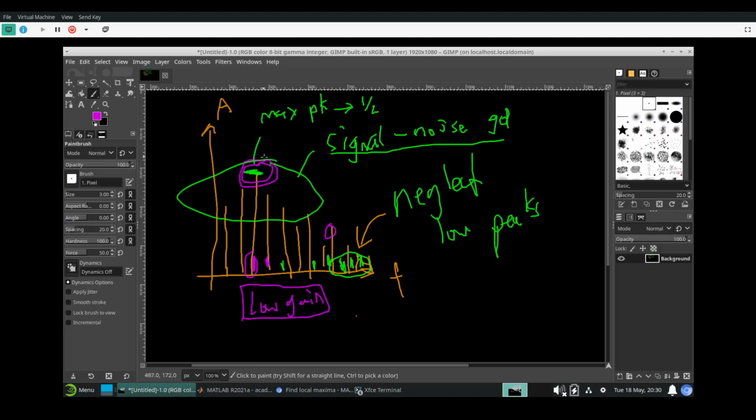How I determine the threshold is to take the maximum input frequency magnitude and divide it by 2, and that's how I determine these are places where I have high signal to noise ratio. Therefore, I will only choose these points to consider my input.